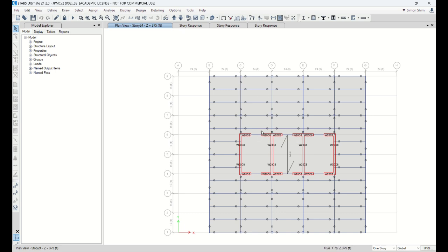So you need to divide the wall, and then define the material properties and section properties for wall and link beam, and you need to draw and assign all section properties so that you should be able to first complete defining the lateral system. Okay, I think I'm gonna stop here, and then we're gonna maybe talk about again tomorrow.